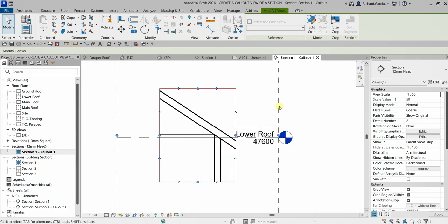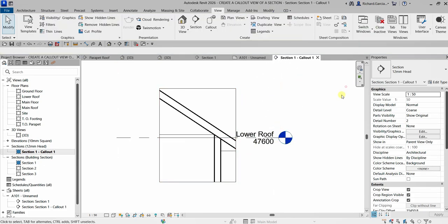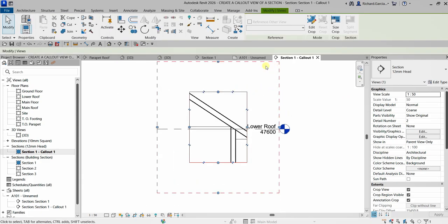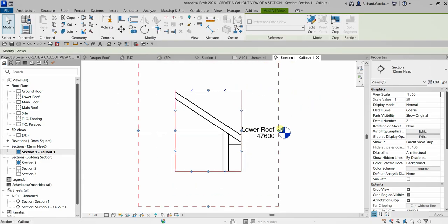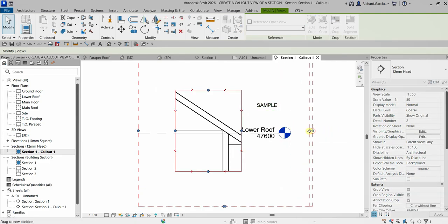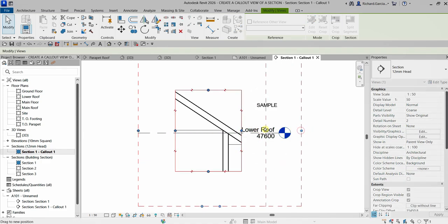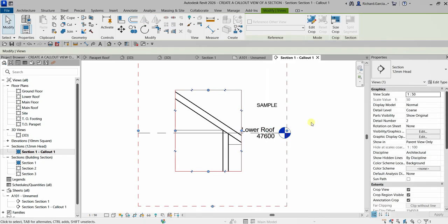As you can see, once your annotation touches or is outside the dotted line, your annotation crop, it will be removed. If I adjust that dotted line, the annotation will show. Once an annotation touches or is outside, it will be removed from view. See? All right, so that's how your annotation crop works.